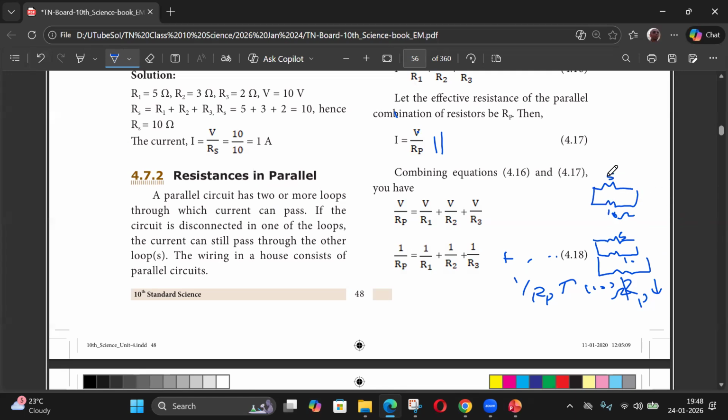See, understood? The first one is 5 and 10 in parallel. The second one is 5, 10, and then 1000 ohms in parallel. So you might think the resistance of this is more because of the 1000, but actually the resistance of this is less because we have a third path here. To go from here to here, I have two paths. In the second one, in addition to two paths, I have a third path. So current is easy to flow. Or I can assume a third path of infinite resistance, which means the path is not there. So you have to compare 5, 10, and infinity in parallel with 5 and 10 in parallel.